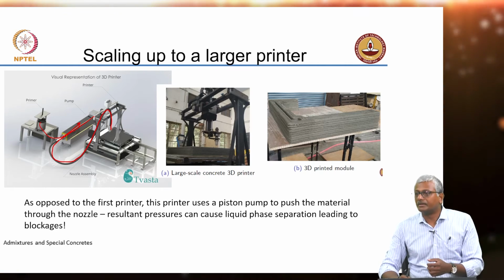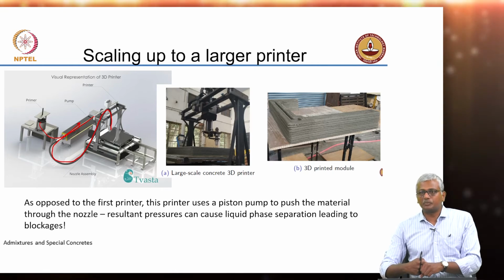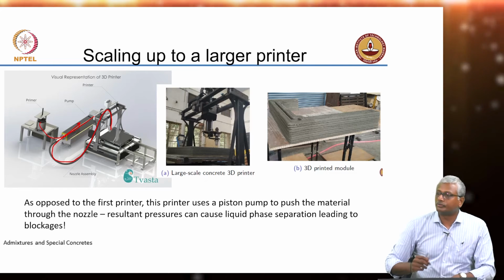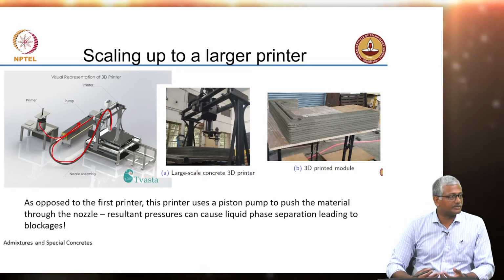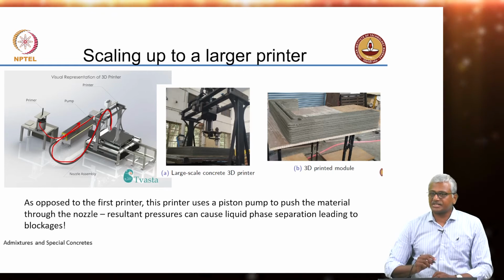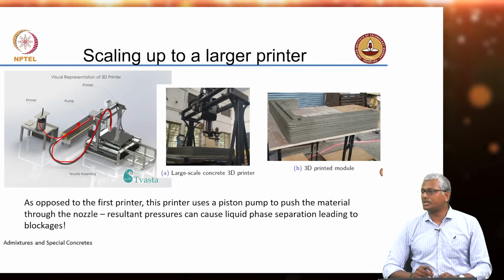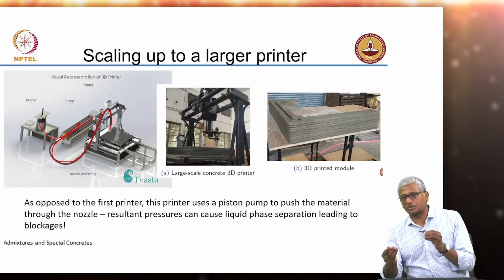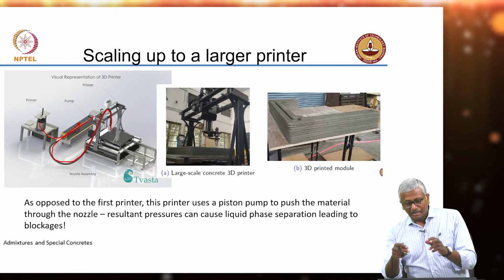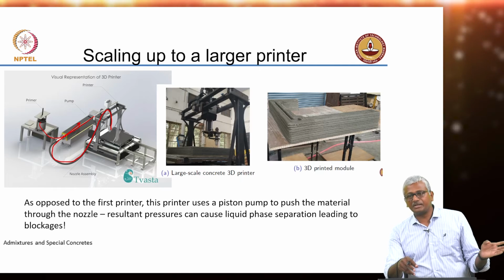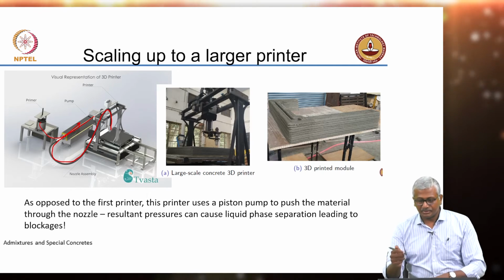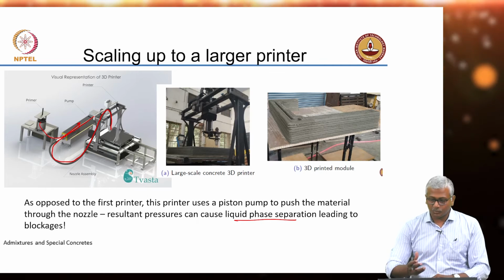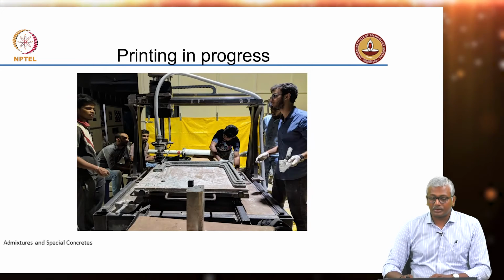But here what's happening? Your pump has to pressurize and push the concrete. Your concrete is traveling through a length of the hose, so it will lose some workability, right? The pressurization further creates an opportunity for segregation to happen, because when you pressurize, the water may separate out. So, in addition to the test that I described previously, you may need to add on one more test to understand the liquid phase separation because of pressure, and that's what we undertook to do in this case.